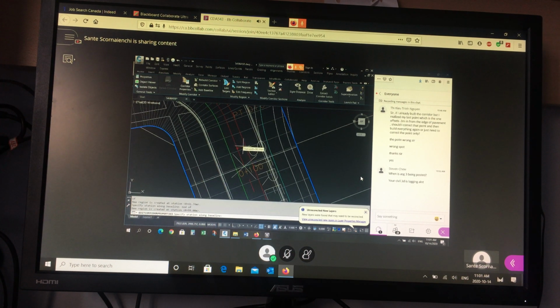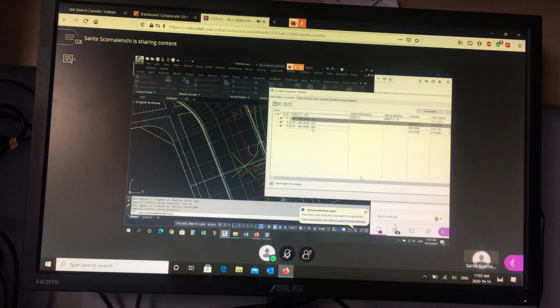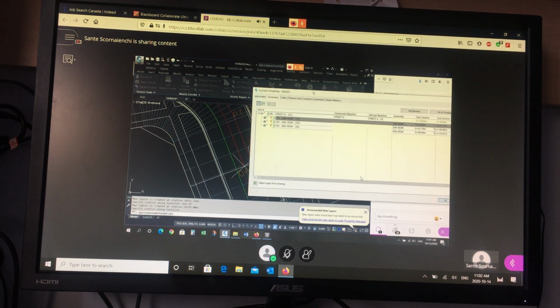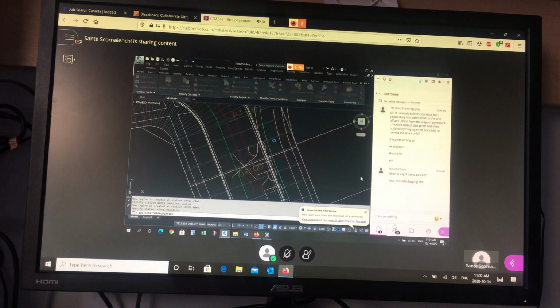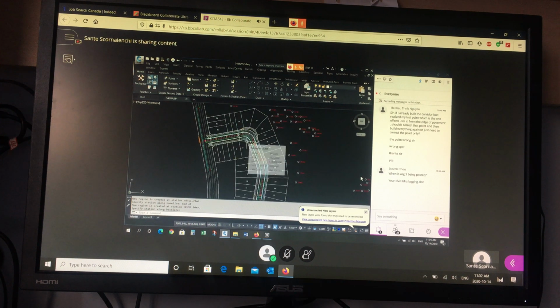There's more chopping to do later, but right now I'm just going to work on this piece. When I'm done, you'll see 3 pieces, and you'll see the warnings. Before you make any changes, just say okay and let it rebuild. You have to select the chopping points and then let it go through the full cycle of actually splitting the region before you make modifications to it. It's not quite a glitch, but it's one of the little fussy points about Autodesk Civil 3D. AutoCAD's a little bit fussy that way. When you pick the chopping points, let that whole process begin and end before you go back in and change things. If you start changing things before you let it rebuild, it gets a little bit fussy.